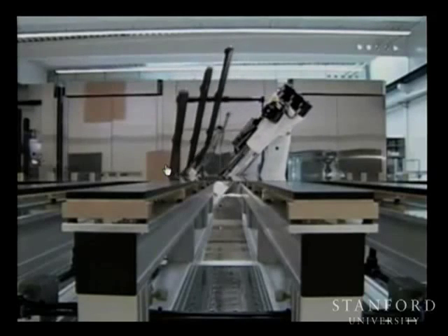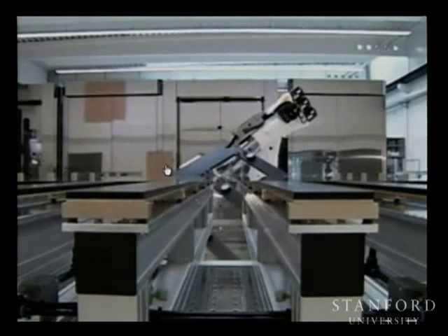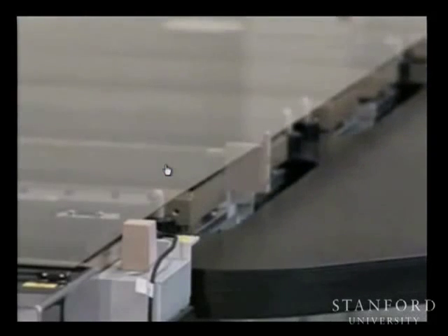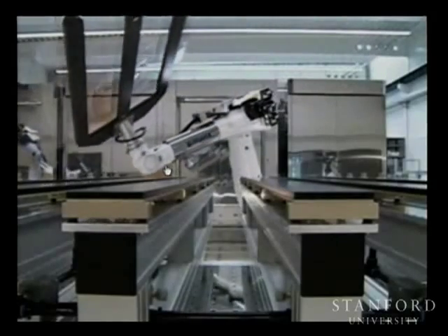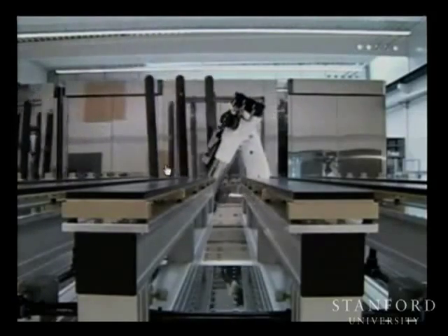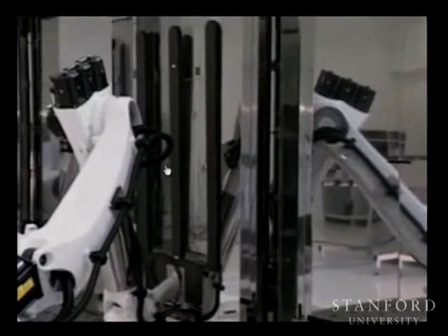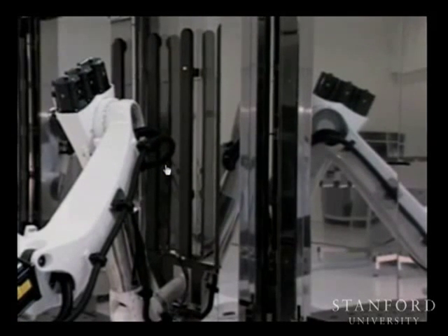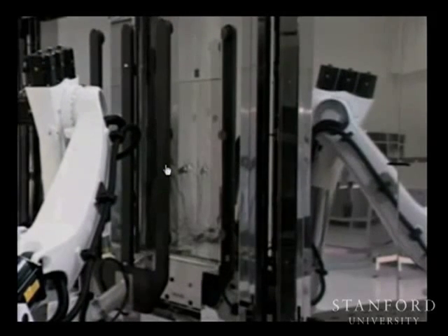So the depth of field that they need, if you remember from your basic optics, goes like lambda over the numerical aperture squared. And so you've got to hold these things. The finer the resolution you want, the flatter you have to have them. So they have to hold that sheet of glass flat within probably 2 to 3 microns over that whole 2 by 3 meter area.